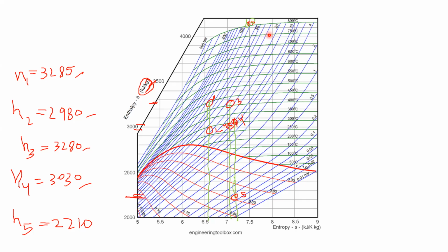Second, at 25 bar pressure only, we have the second state. For that, in this line, where the 25 bar line is met at this position, I have to mark that position for finding the enthalpy at the second state. The 25 bar line may start at this position. If you extend this line up to this vertical line, that will give you the second state. For that, you have to take the enthalpy value.